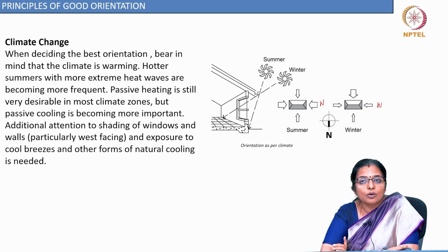When deciding the best orientation, keep in mind that the climate is warming. So, hotter summers with more extreme heat waves are becoming more frequent. So, passive heating is still very desirable in most climate zones, but passive cooling is becoming more important, because you should also notice that along the tropics, passive cooling is a very important strategy that is required, especially because a number of developing countries are also along that belt only.